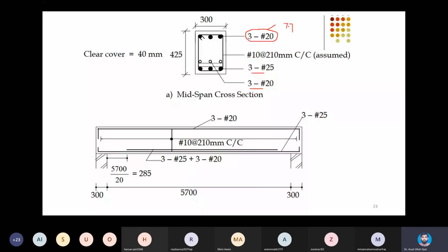But on the tension side, you are not doing any correction. It is 2313. Obviously, when you consult the nominal bar tables, you will find that nominal areas may not be exactly equal to the theoretically calculated. You need to do a little round up. While rounding up, don't round up to a larger extent. Within 1 to 2%, try to finish the selection.